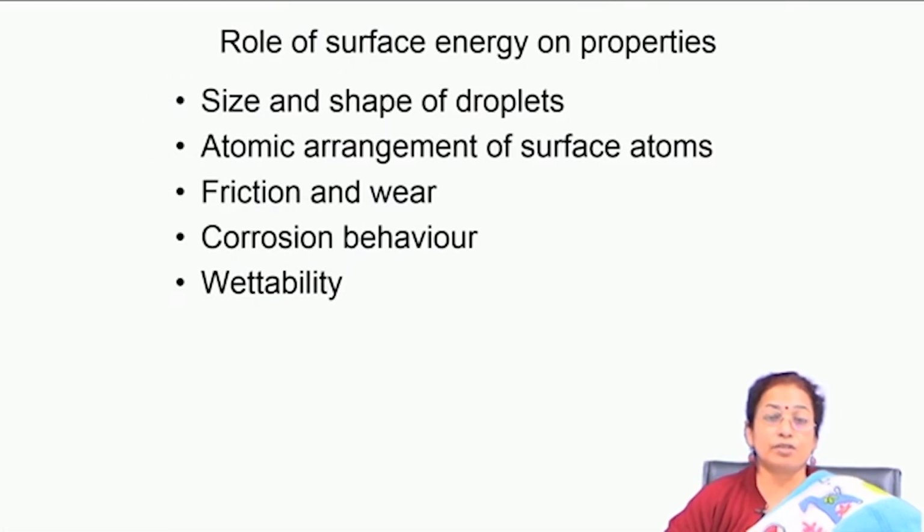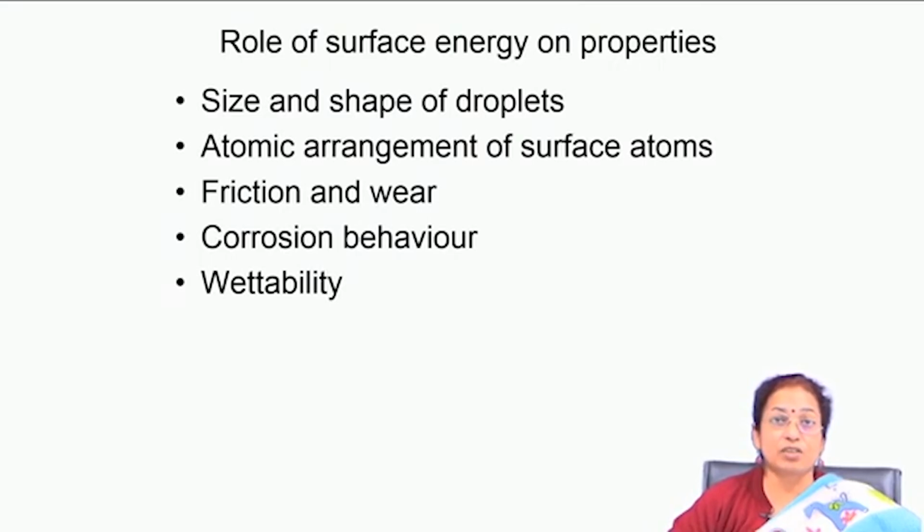Now, if you talk about the role or importance of surface energy, you will find that it influences many important phenomena, like the size and shape of droplets, the atomic arrangement of surface atoms, friction and wear behavior, corrosion behavior, and wettability. These phenomena all depend on the surface energy, and the driving force is the free energy change associated with lowering of surface energy. Whenever you create the surface, there is an increase in energy, so naturally the driving force is the lowering of its energy.